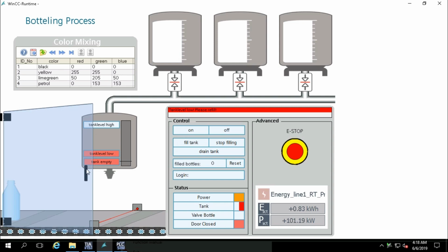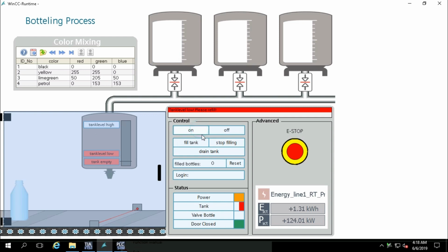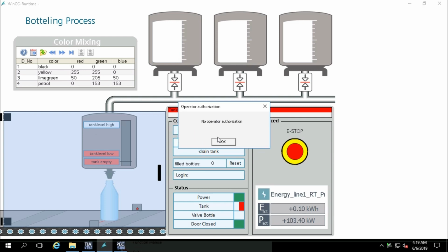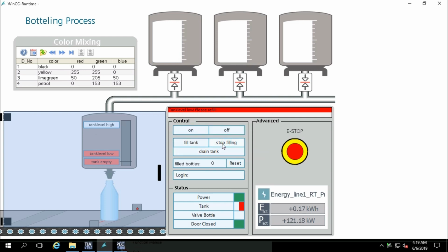And you click this button up here in the header. And the connection should be established. Of course, the PLC Sim Advanced instance has to be running, so it should blink, or the green LED should be visible.